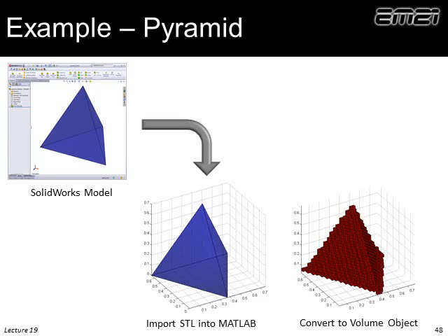So what does this look like? Well, let's say we go into a CAD program and we build our pyramid. We import that into MATLAB and we use a command like patch that would draw it, and then we run the algorithm on the previous slide and we can fill in a 3D grid with that pyramid. Now we're ready to model this with something like finite difference time domain, finite difference frequency domain, rigorous coupled wave analysis, any number of things.